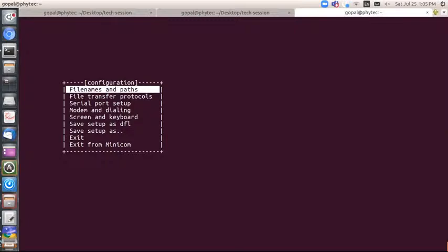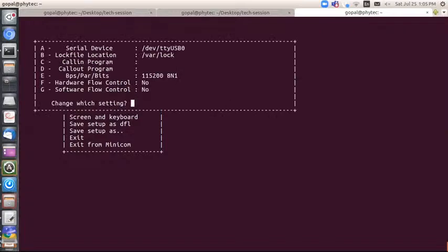For the port which is needed, there are a few parameters we have to initialize. Practically, if you see, the serial port setup is there. These are the list of parameters it asks you for before establishing the communication. Just make sure your socket gets ready with some information. Here the port is the device recognized as /dev/ttyUSB0.